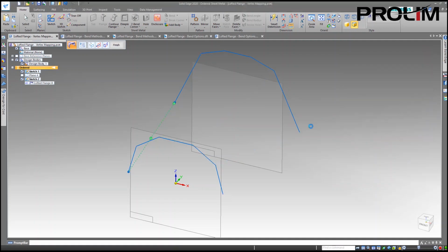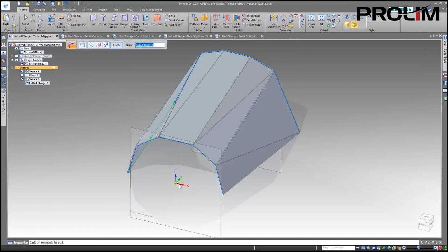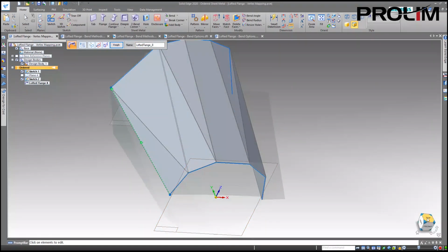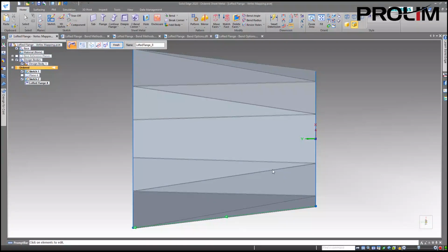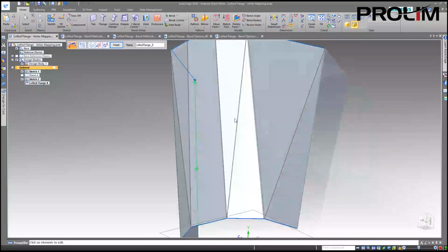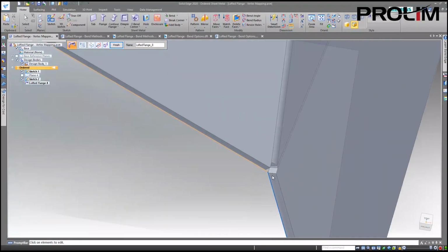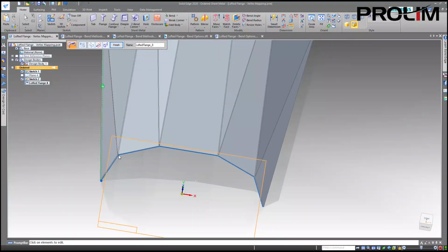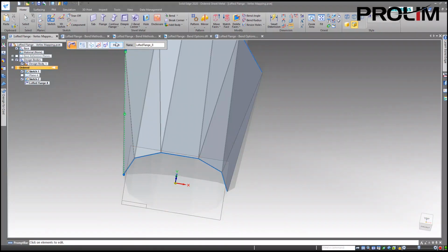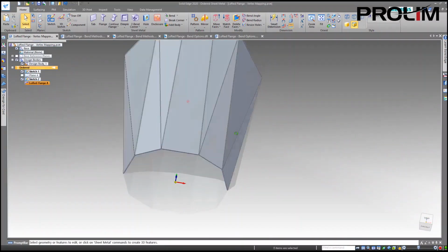Okay, pretty simple. We'll hit OK. It'll recalculate the part. And now you can see that if we look at the top view, now we're much more symmetrical. All the angles are kind of going in the right direction, all towards the center of the part. It got rid of the little auto relief that we had over here that didn't match the other side. So it gave us the desired result within just a few quick seconds.